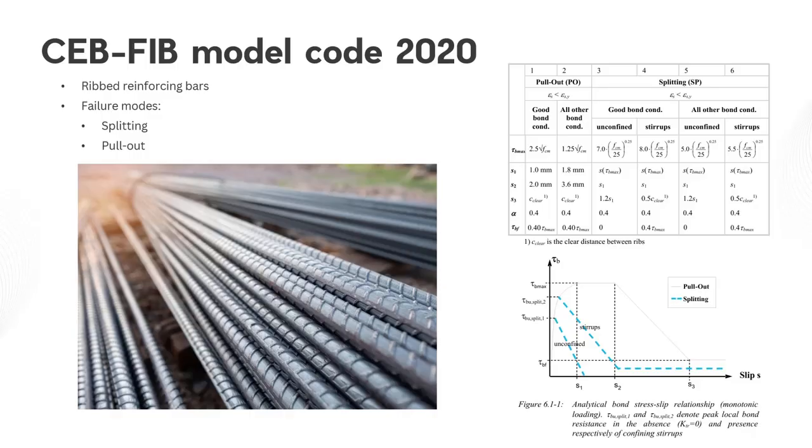The mechanism leading to the failure is that the rebars transfer the force through shear forces along the interface between the concrete and the reinforcement rebars. The concrete between the ribs progressively shears off, and the bar slips out without major cracking.